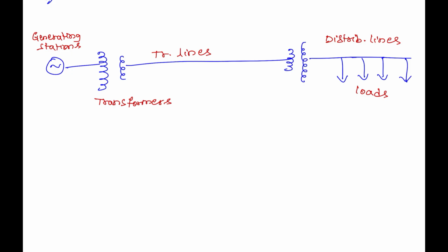These are the major components of a power system network. All these components operate at different voltage and power levels. The generator has an impedance value based on its own voltage and power ratings. The transformer has an impedance value based on its own ratings. The transmission line has some impedance based on its own voltage level, and the loads also offer some impedance or admittance values based on their own ratings.